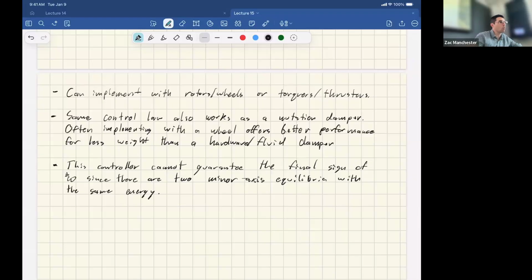There's a couple ways around this. One argument that I just made is you can resort to noise and say, there's noise and that thing's unstable, so it's not really a problem. The other way to get around this is that the theorem applies only to time-invariant vector fields. If it's a constant control law, a constant vector field, and you make it time varying, you can wiggle that point around in a time-varying way, which also gets rid of the issue. But again, if there's noise, it's not an issue.